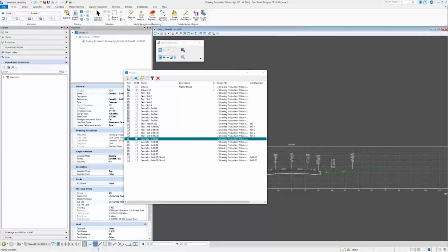Let's see. Next one. How do you recommend updating name boundaries when your alignment has changed? Seems that recreating the name boundaries is the only way. That is what we recommend. If you are going to be making changes, we always recommend recutting. It works way more often than just hoping everything updates dynamically.